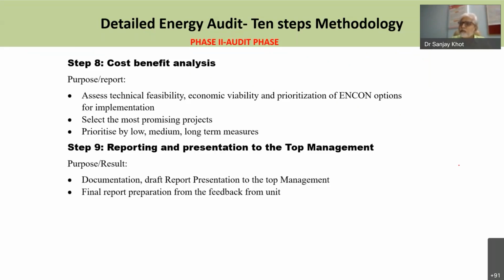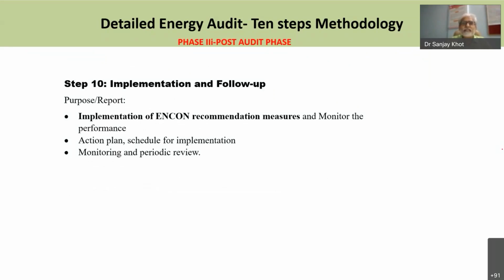And the last step of the detailed energy audit is the implementation and follow-up. Suppose you prepare the report, present it to the top management, and it has been submitted. That much is not the whole work of the energy auditor. The energy auditor has to take the follow-up till the implementation of all the suggestions made by that energy audit. And for that we have to prepare an action plan, a schedule for implementation, and monitoring, as well as periodic reviews, which are also very important.